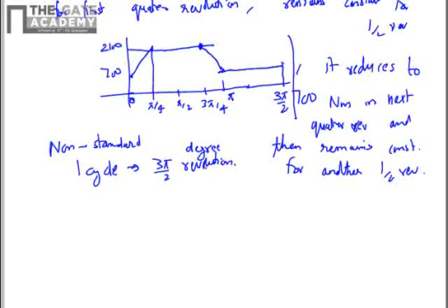It is not necessary in the flywheel calculation or any calculation that the cycle should cover 2 pi. In 3 pi by 2 also, if one cycle is getting completed, we can calculate for that. So we consider only this portion of the cycle, from 0 to 3 pi by 2, and one cycle is done and then the same thing is repeated. We will analyze only this much portion.